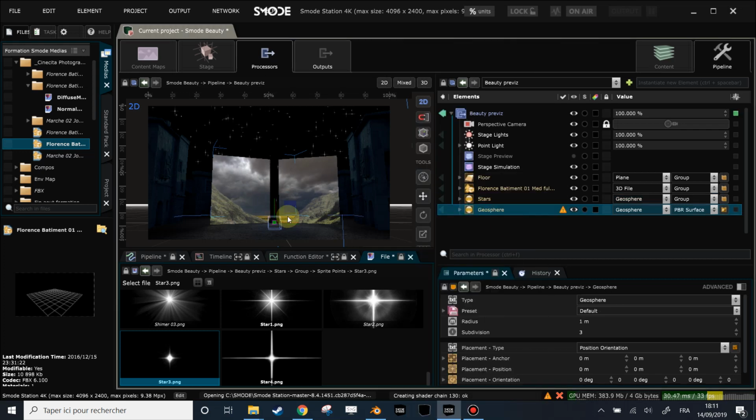because I have no explanation why, but that's it. Okay. So if you have trouble selecting 3D element from the 2D viewport, be sure that you are in 3D selection mode here and not in 2D selection mode, so that's maybe why you have trouble selecting your stuff.